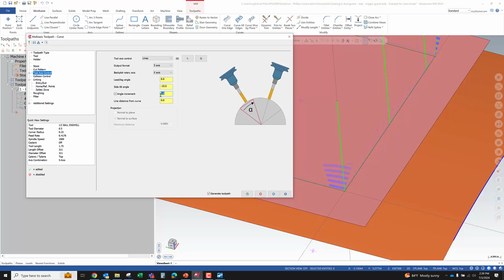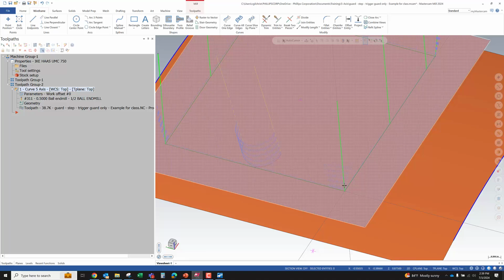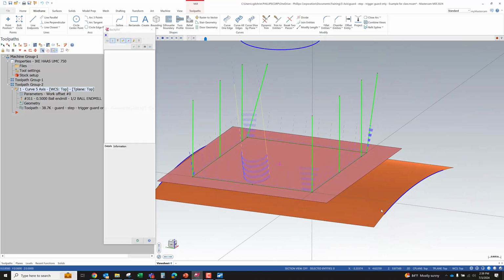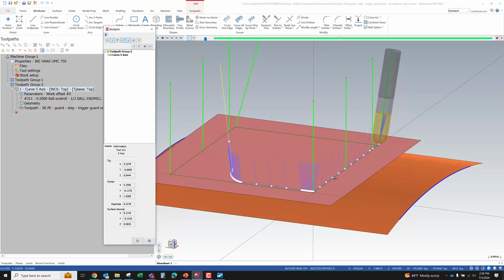I've used as small as 1/100th of a degree, but somewhere between 3 degrees and a half degree is a pretty good value to use. So this would be buttery smooth and actually a pretty decent tool path if we had to cut this square.